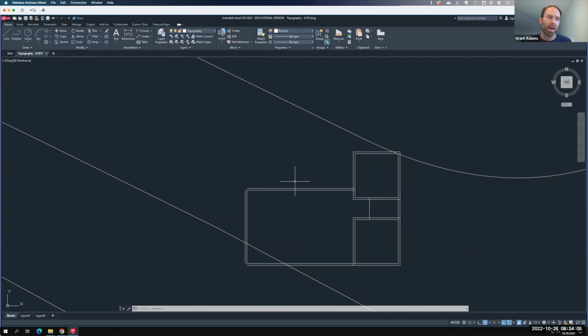So at some point your wall gets thicker than that anyway. So 6 is kind of a generic term. Since this is not a construction class and it's not a working drawings class, I'm happy if you draw it at 6 inches or 4 inches, that works for me. If you want the interiors to be thinner, you can absolutely do that. I'm just staying consistent to make life easy, but you're entirely correct.